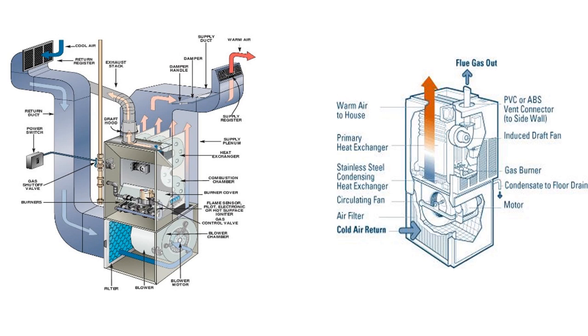Now that we have looked at the different fuels and how to distinguish between oil-fired and gas-fired appliances, let's take a look at the types of furnaces and their common basic parts. Furnaces heat a conditioned space by convection. Furnaces use ductwork to deliver the heat it produces to the conditioned space and bring the cooler air back from that space to be heated. Furnaces have a supply duct and a return duct. The supply duct is the one that delivers the warm air to the conditioned space. The return duct is used to bring cool air back from the conditioned space.